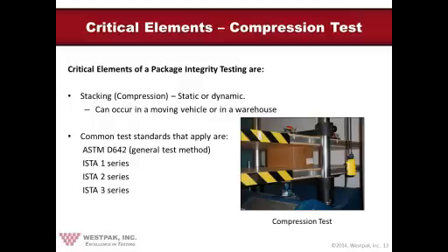So let's look at compression testing, or stacking, which is another key element in the package integrity test. Each standard has a formula where you plug in either the dimensions or weight, or both, of the package system, and a specific top load is provided. These formulas add safety factors to the required top load to account for all the variables affecting stacking strength. Shown here is a compression test system used for static compression tests that are seen in ISTA 2A or ASTM D4169.